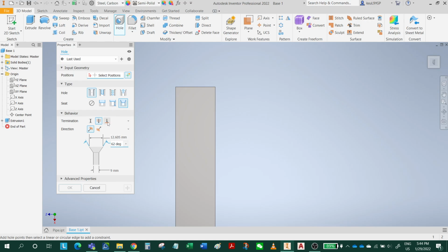And this is the through hole. If you see a red minus sign here, it doesn't allow the center point creation. If you put the cursor here, it says allow center point creation is off. Then you click here, and you can add the hole in the part.